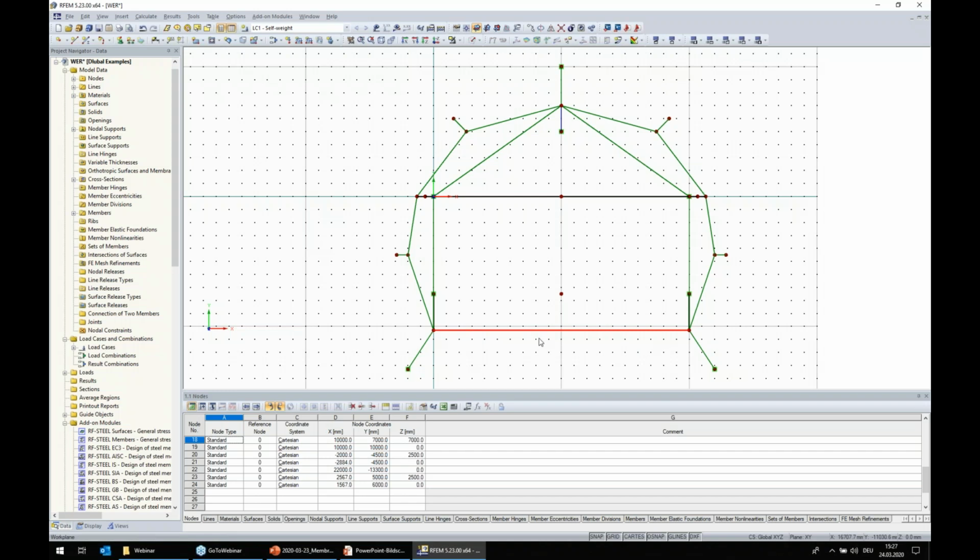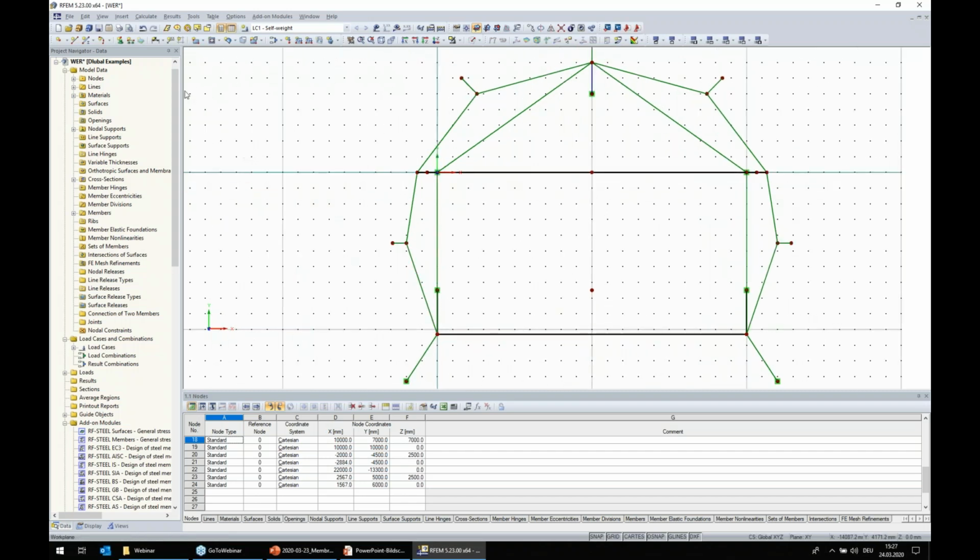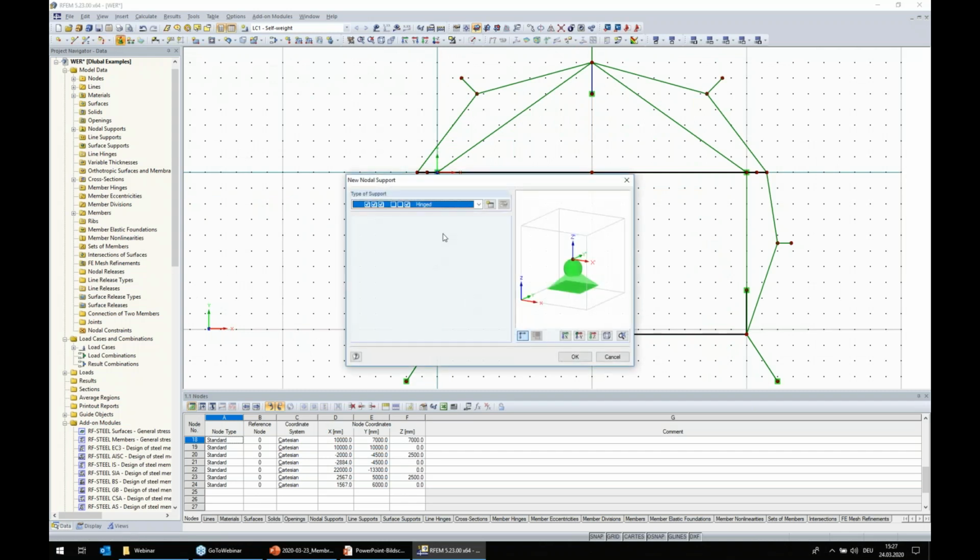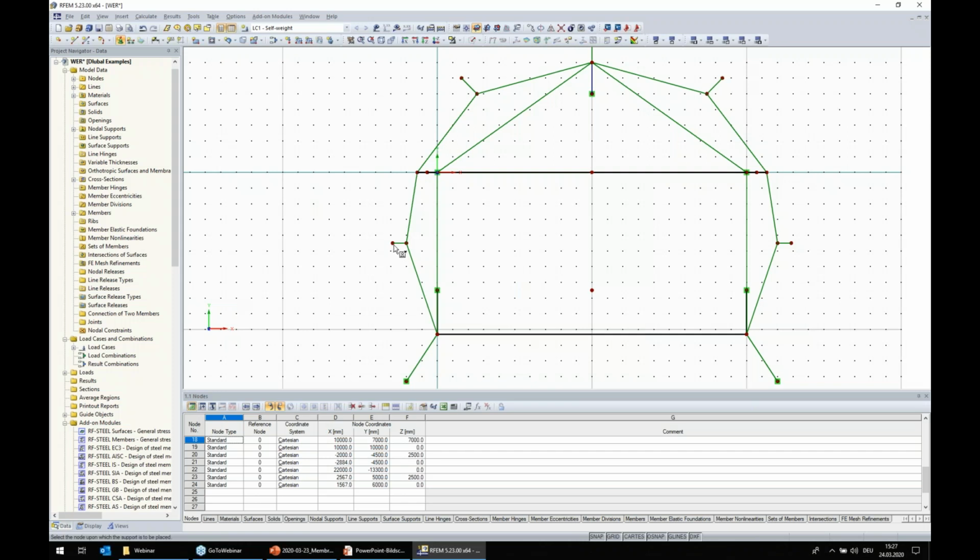The membrane will connect to the straight beam here and to the cables around, and could so give its forces to the basis construction. The only thing what we have to do now regarding cables, we have to apply the remaining supports, what means these span cables should be fixed on bottom.